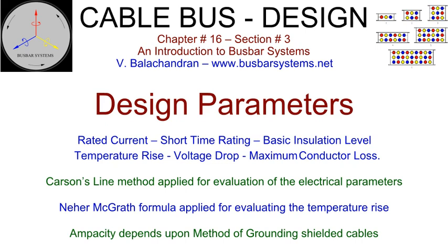The slotting of the cables in the phase is carried out in a manner that provides minimum unbalance and least voltage drop. This optimization can be carried out in a computer program. Phase transposition of the conductors is not carried out in cable bus. Having conducted type tests and field measurements on different types of cable bus, most of the reputed cable bus manufacturers will be able to justify the design, interpret the computer output, and forecast the results.